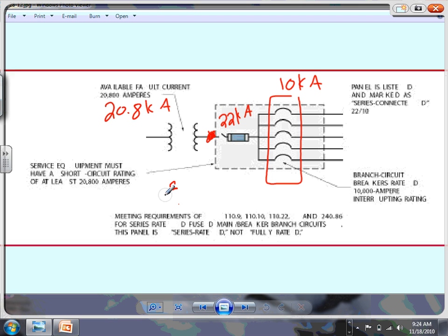The way they work, guys, by manufacturer, these two circuit breakers, the main, the fuse, and the circuit breaker, work together. If I have a short circuit right here, and the short circuit here is 15 kilo amp, look at the scenario, a 15,000 amp short circuit. This circuit breaker, which is rated for 10, will see that there's 15 going through it and will do nothing, would not try even to interrupt it by design. And it waits until the main interrupts it.